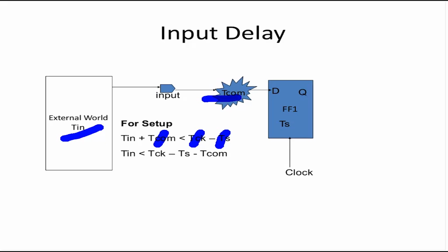Please note again, it is a setup timing constraint. You need to represent this equation in the form of estimate less than constraint, less than sign, estimate less than constraint. Again, this is the estimate part, this is the maximum that it could have. So estimate less than the max delay constraint is the max delay equation or the setup equation. So how do I estimate an input delay?